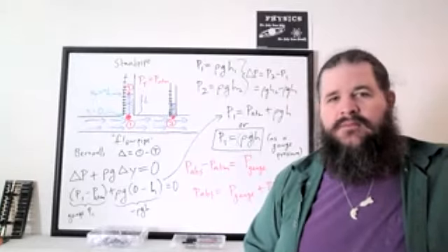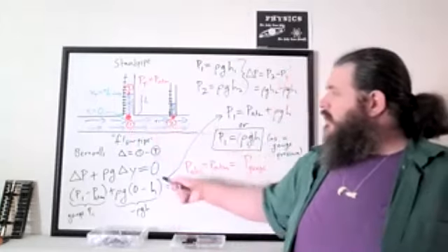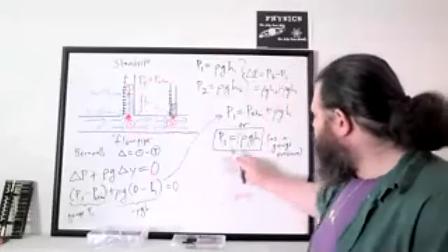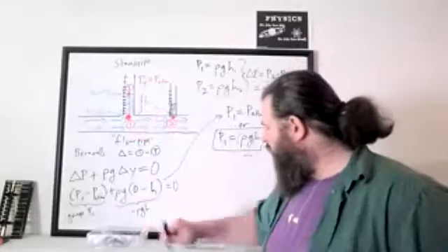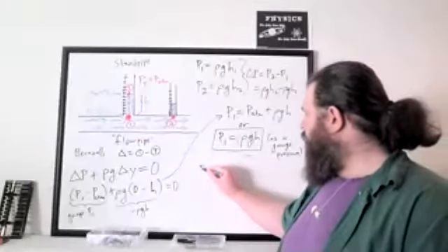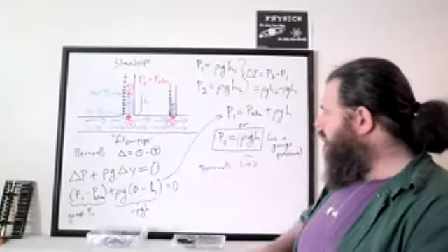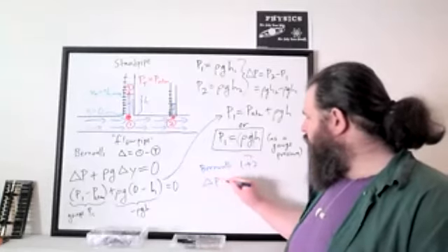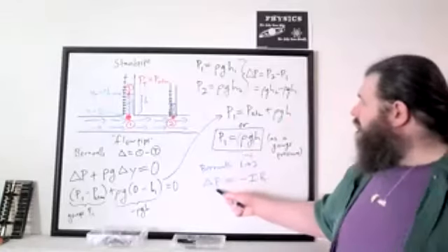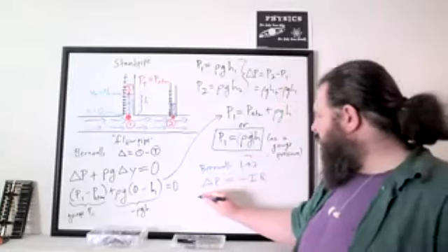Resistance? Yeah, presumably there's resistance in this pipe. So we're losing pressure in the direction of current. Current is flowing from a high pressure zone towards a low pressure zone. So if we set up a Bernoulli equation from 1 to 2, then we have delta pressure equals negative IR. That delta pressure, P2 minus P1, is just rho gh2 minus rho gh1.